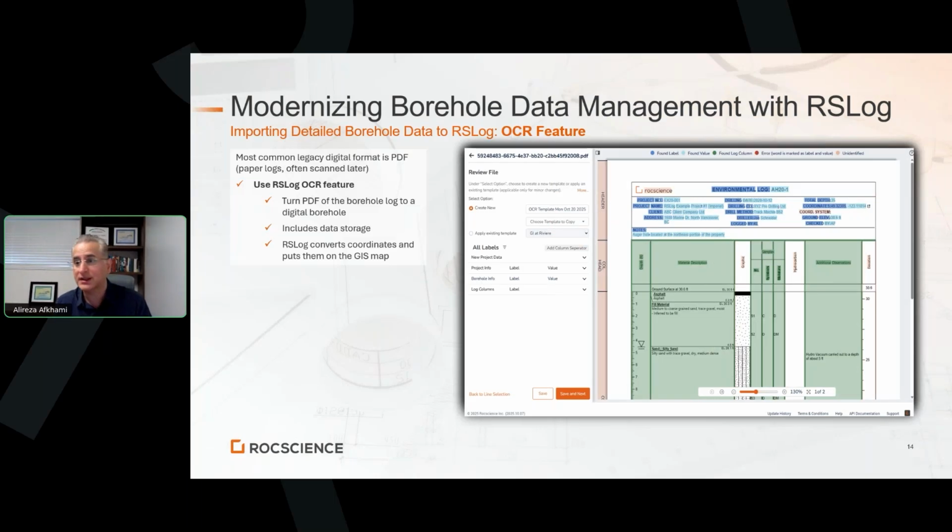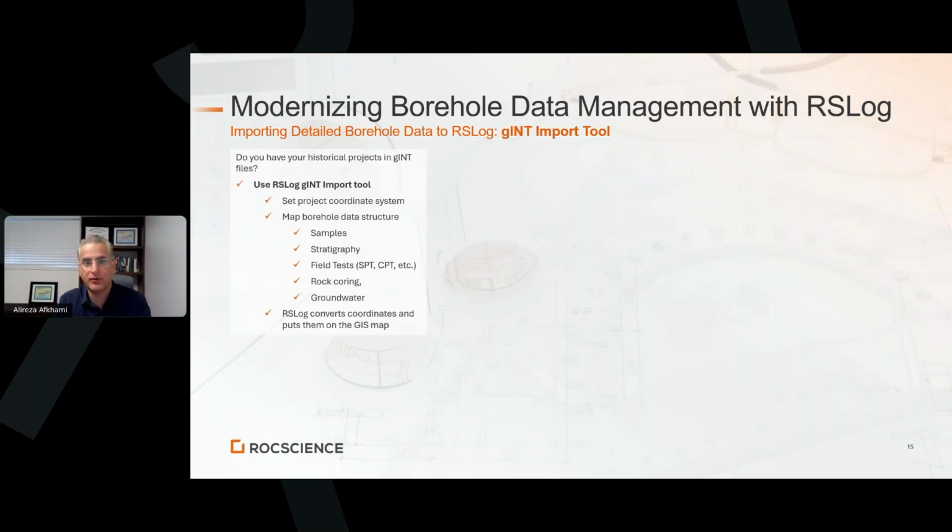And what happens is the data will be automatically imported, the extraction will be done, and if you have coordinates on these borehole logs, they are going to be immediately on the GIS page, or on the GIS map in RSLog.